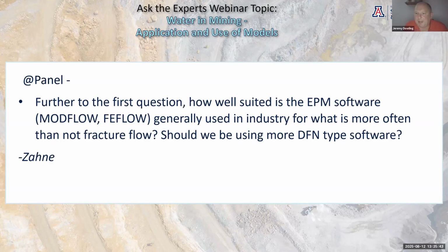Yeah, I completely agree with that. You'd have to understand the hydraulics of all the fractures in order to make it useful, and you can't possibly do that. It's all right to understand the fractures themselves, but then you need to understand whether they're full of mineralization, calcite or clay, or they're just mechanically closed or discontinuous, because then none of that helps with groundwater flow and movement.